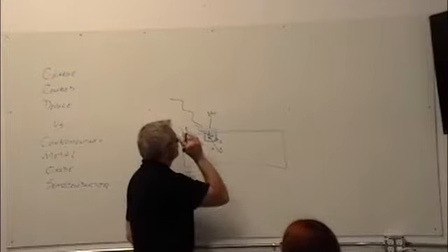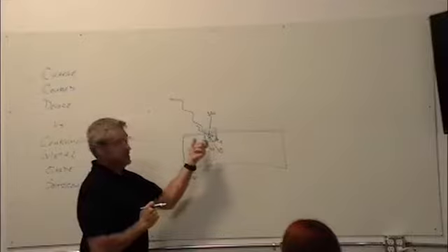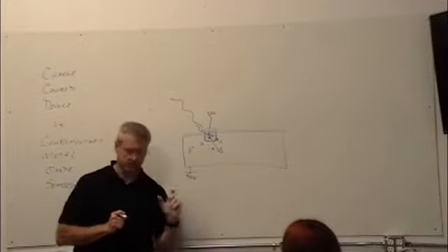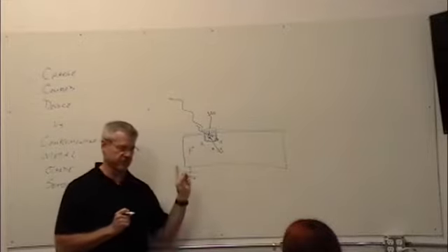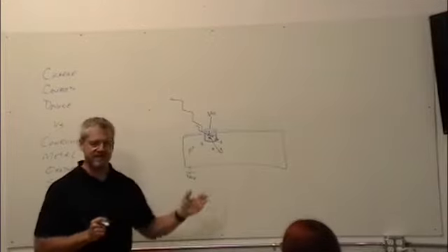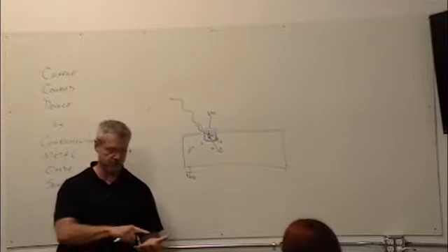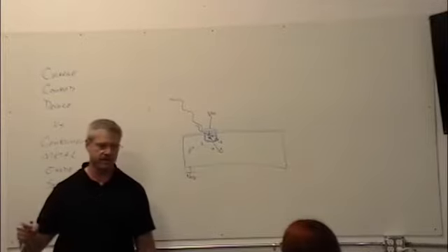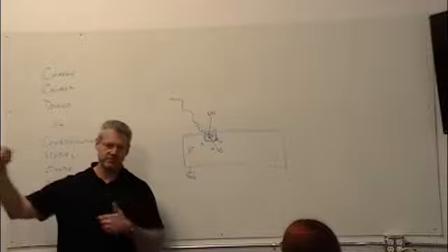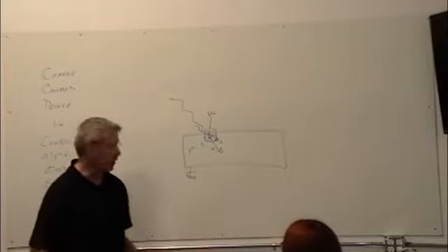Now I have electrons stored. And I can look at that. First of all, this is called a destructive readout because I have to basically empty that to find out how many electrons are in there. But I can look at it and say, oh, for every electron that was there, that was a photon, and you can do some math and come out and say there was this much energy, it was this bright, it was whatever.